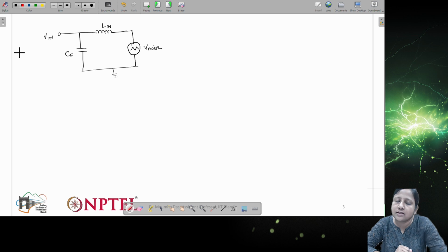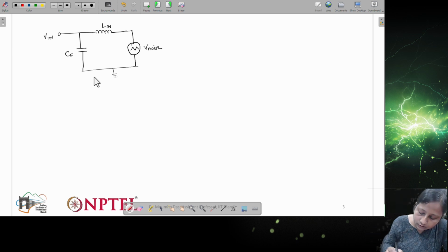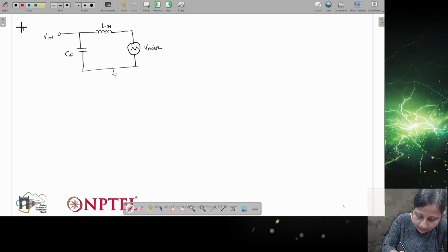Now in the last class I discussed that this filter can be any type like LCL, CLC, T type, pi type, any filter can be there. And I have also discussed the different components of the filter, right? So here I am just showing the simple LC filter and how we can connect this to an active filter, and where exactly the difference is coming. So if you see here, this is the one which you know as the passive filter.